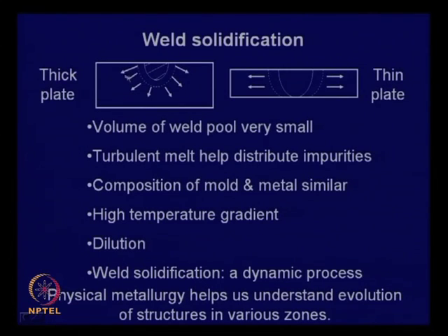Schematically, the heat transfer is shown here for two cases. First, thick plate. Imagine this is the molten pool, and surrounding it a thin layer gets melted and mixed up with the weld pool. Here the heat can flow in all directions, through the thickness direction as well.